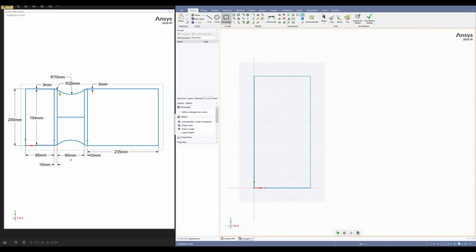After that, I'm going to create the middle rectangle here, this rectangle with 90 millimeter width. So we can again use the rectangle, but this time I will go in the options menu and scroll a little bit down and use the Cartesian dimension. By this tool, I can define the starting point of this sketch. First of all, I will select an origin point.